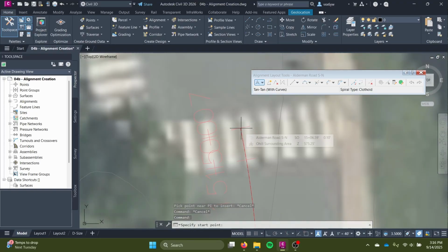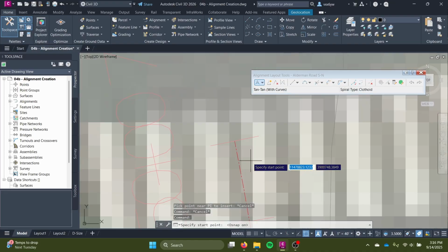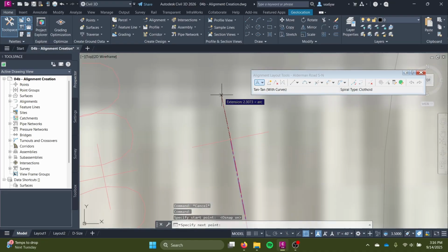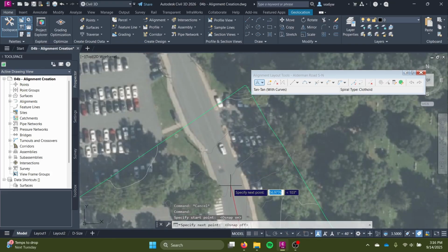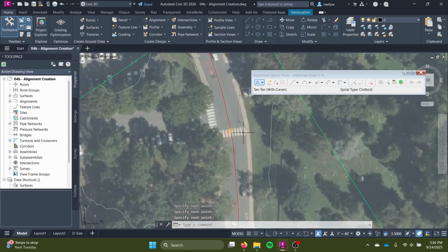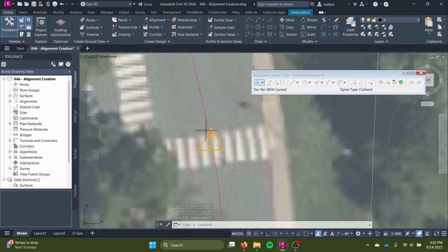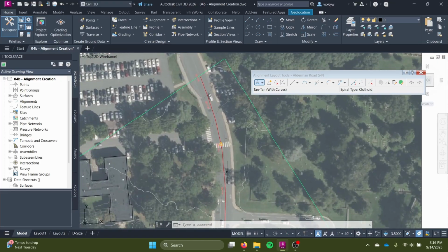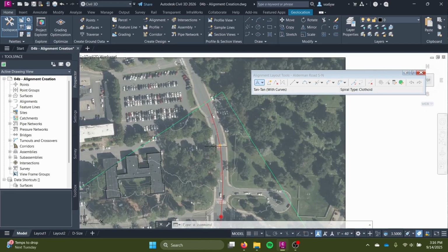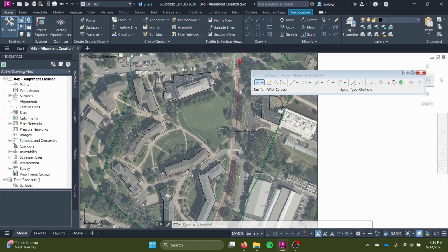Now, importantly, I'm going to turn on object snapping. I'm going to hit F3. My object snapping is on, just so I can exactly align the points here, and then I'll turn it right back off. And then you can continue with modeling your alignments. You can see those all updated. That's just showing a marker because it is joined together, but those are two distinct drawings I made, I guess, is one way to look at it. And so that's Alderman Road.